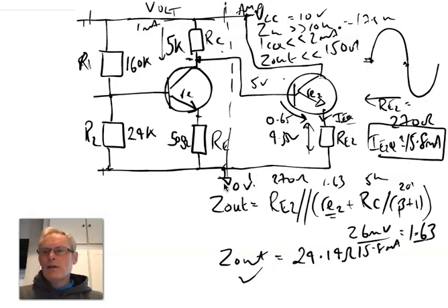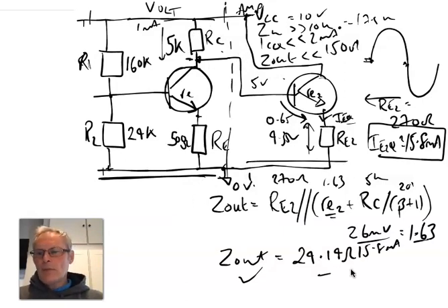But this hopefully demonstrates that, without changing this stage in any shape or form, we can add a voltage follower which can then make our amplifier drive much smaller loads. We could modify this even further. We could increase or reduce RE2. By increasing it, we're going to relax and therefore decrease this quiescent draw even more. So again, play around with the equations and see what you can come up with.